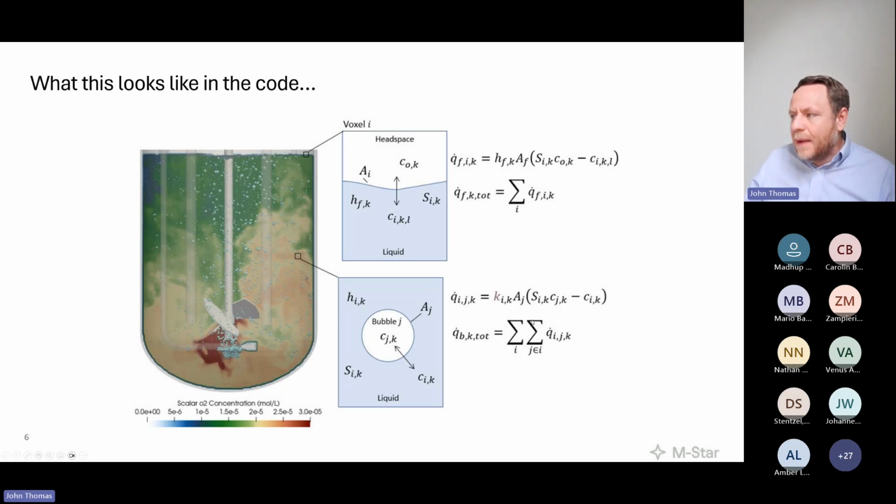So we have Q dot on a per bubble basis in one individual voxel of fluid, that is the neighborhood of fluid that contains that bubble, for a given species, is going to be equal to the convective mass transfer coefficient around that bubble, which would be a function possibly of EDR or flow rate, should we choose it to be. It'll be a function of capital A, not lowercase a yet, capital A, the area of that bubble, and then the driving potential within the bubble versus the aqueous phase. This is familiar except for the capital A aspect to some people, but we'll come through that.